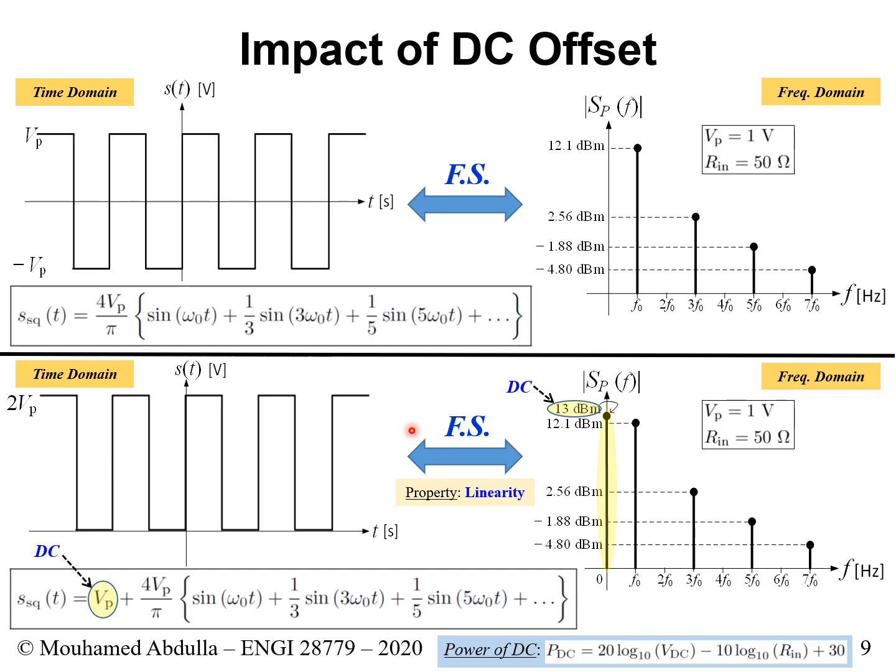If, on the other hand, your signal is odd, like this one here, you know for a fact that there is no DC component. If you have a signal like this, that is neither odd nor even, then there is a big likelihood that there is a DC component. In fact, the DC component is very probable.